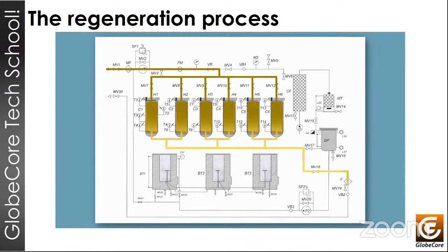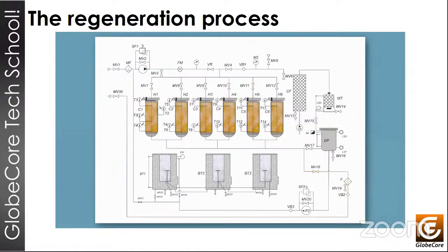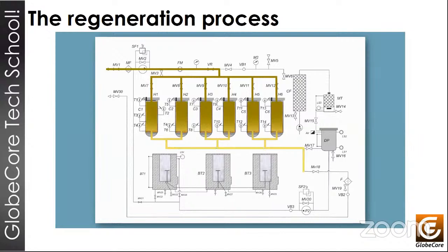It's very important to carefully manage the processing rate, as one of the main variables in the regeneration process is the time that the oil spends in the columns, or retention time, right? So the passage of oil at reduced speed, at a reduced rate, can actually improve the results of the process. And as soon as the capacity of the Fuller's Earth is fully exhausted, it needs to be reactivated. And this process we can see in the next slide. Next slide, please.